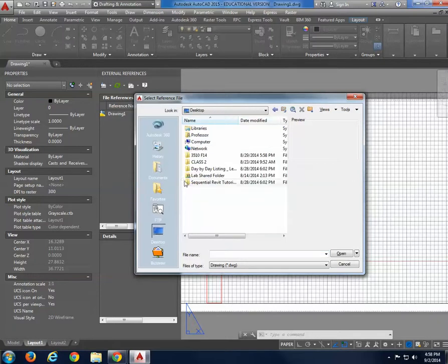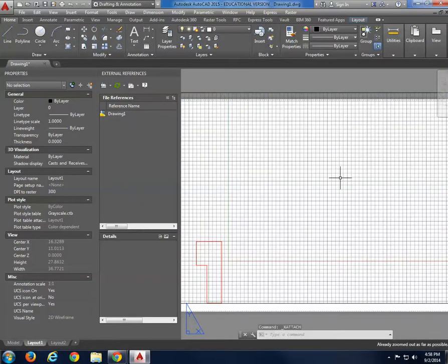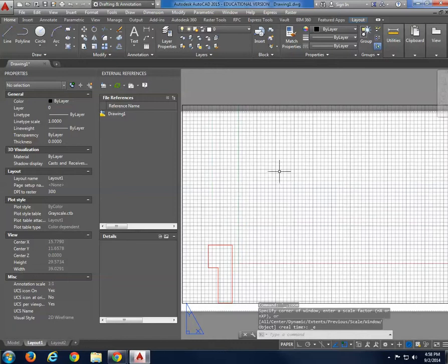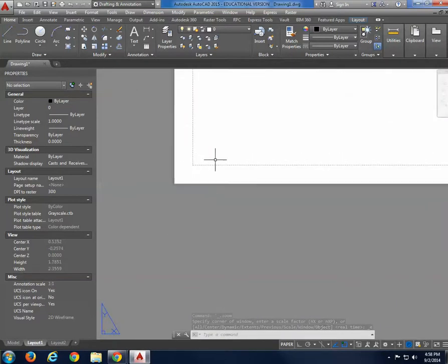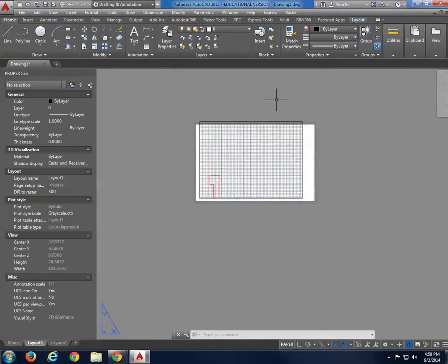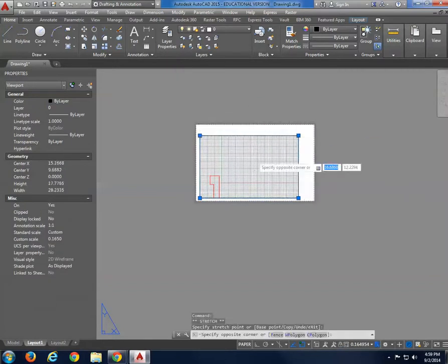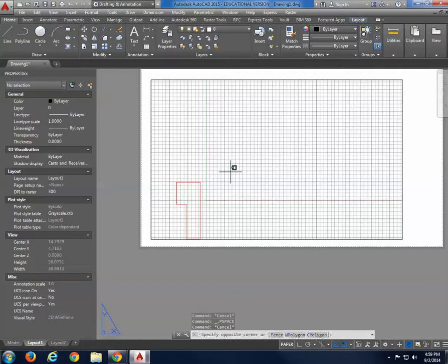So what you would do is just select the title block, and it will automatically be placed here in place. Remember that when you place it, it comes assigned to that point, the 0, 0, 0. So make sure you move it to that point, which is the real place that we want to have it. Okay, so that's pretty much repeating myself, but remember that you can double click to get in, zoom, extend.